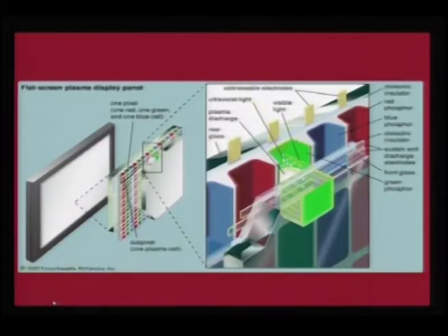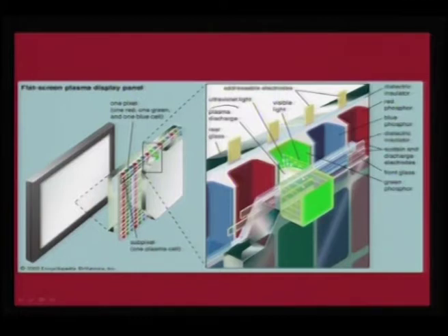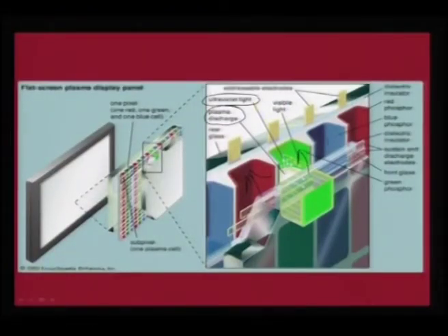This same phosphors can also be used for plasma display panels, and as you would see, the display mechanism is quite different compared to the CRT applications. In this case what you see is a plasma discharge, and this plasma discharge is actually brought about by the UV light, and once UV light is generated in the back panel, that UV light will shine on the respective ones red, green and blue, and as a result you will get a plasma which is generated that will account for the emission of full color display.